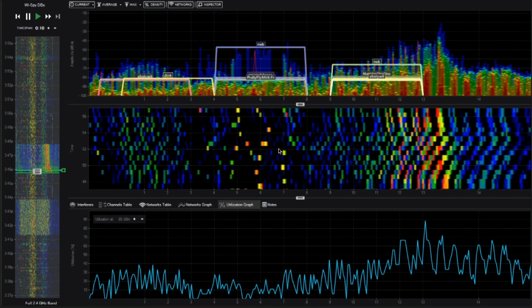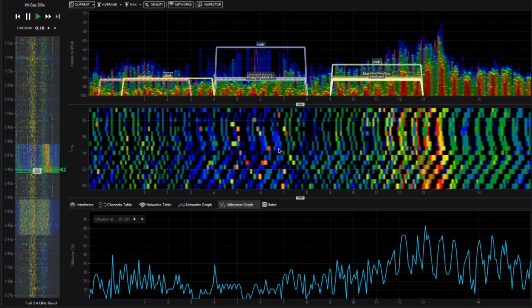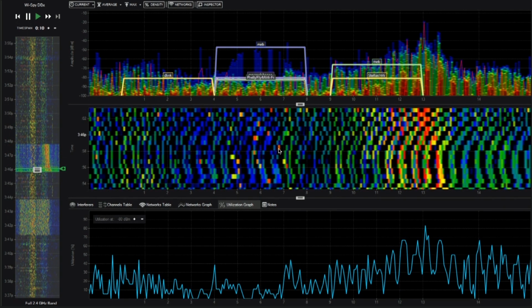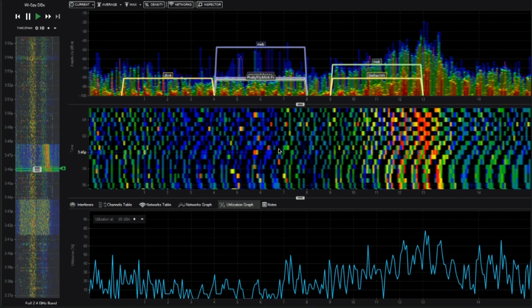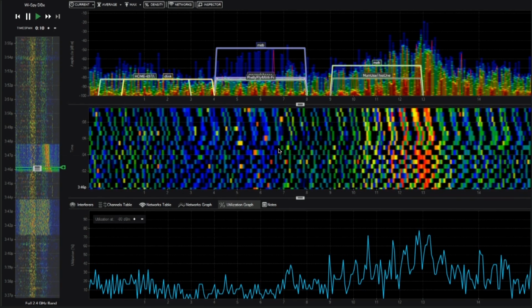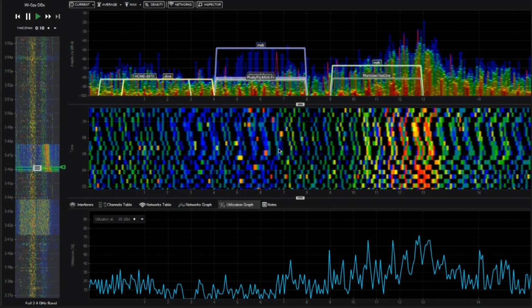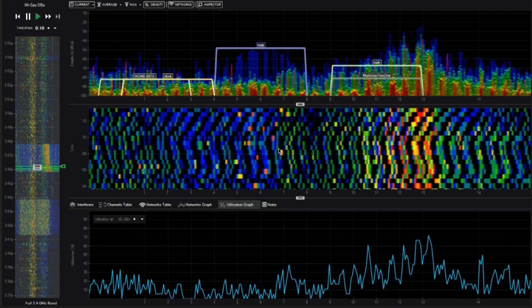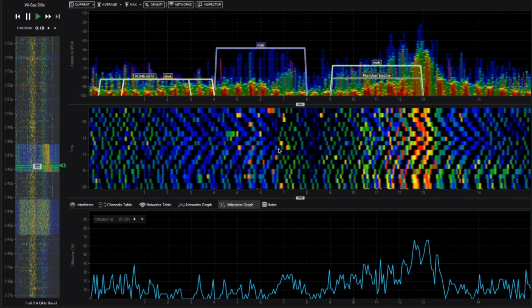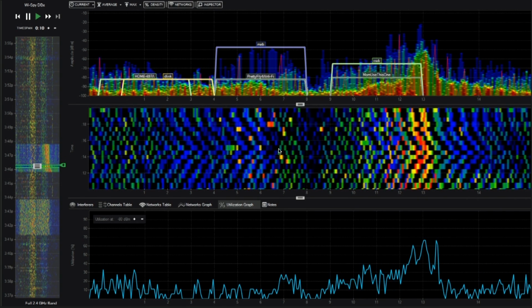And it's a little hard to see in this interpretation, but you can see this pattern of high-density transmissions that appears almost immediately. And this will just sit there and sustain until the microwave stops running. As soon as the microwave stops running, that transmission just vanishes, and it goes back to normal in a period of 3 or 4 seconds, and all of a sudden that interference is gone.